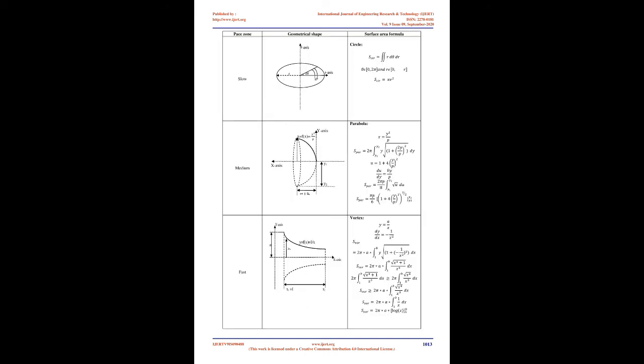For identifying a specific reaction regime, the classification was further modified based on other attributes, like initial acid concentration, initial extractant concentration, stirring speed, and phase volume ratio, and their dependency on the rate of reaction. Among all the attributes, we have focused our study on stirring speed because there is a variation of geometrical shape and available surface area for contact with respect to stirring speed. As such, the interfacial area between the phases will influence the design of a reactor. In this work, four phase zones, slow, medium, fast and very fast, were proposed based on stirring speed in the Lewis stirred type cell. Each phase zone resulted in a specific geometrical shape. Based on the geometrical shape, available contacting surface areas are theoretically correlated with the rate of reaction.